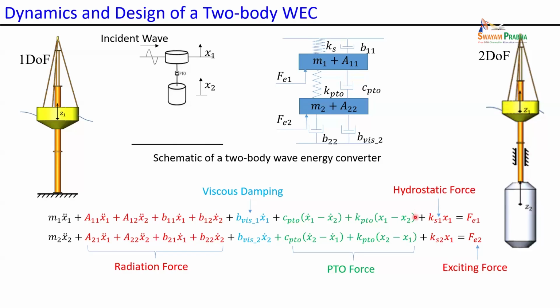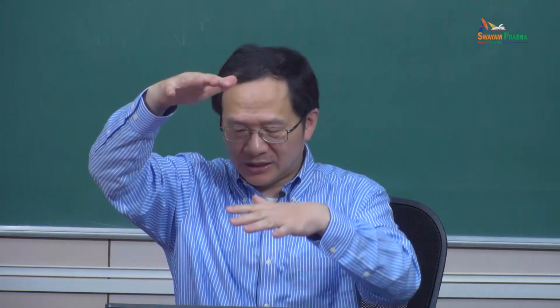So then you have excitation force. Excitation force depends on how deep that is. You understand? And if the depth decreases to a quarter wavelength, then the amplitude of water motion is already decreased to 23%, right? So most likely the force on this is small. Okay. However, there's still force here.